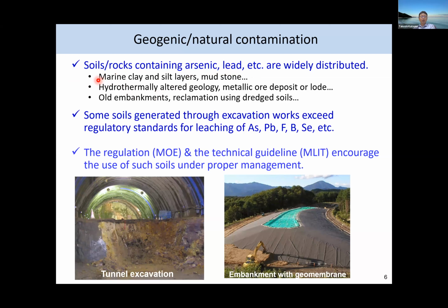For example, in marine clay or silty layers, mudstone, or hydrothermally altered layers, or embankments coming from marine clay or hydrothermally altered geology, or reclamation using dredged soils. So some soils generated through excavation works at construction sites exceed the regulatory standards for the leaching values of arsenic, lead, fluorine, boron, selenium, etc.